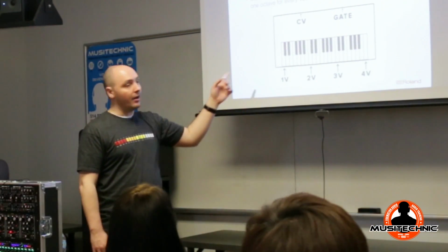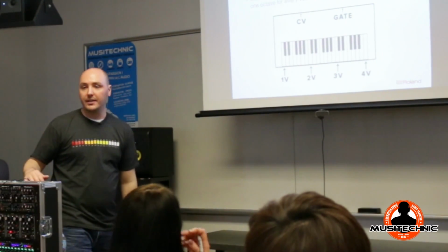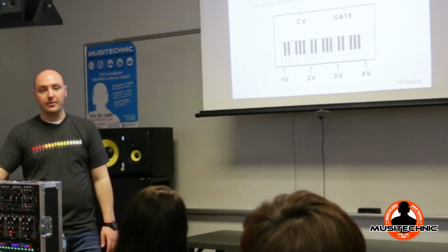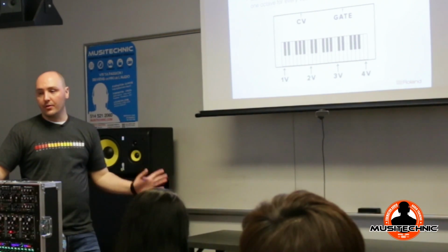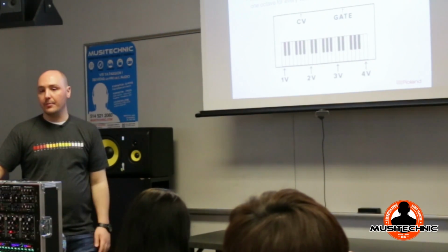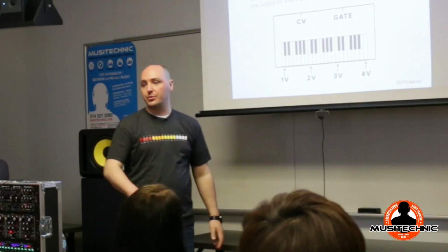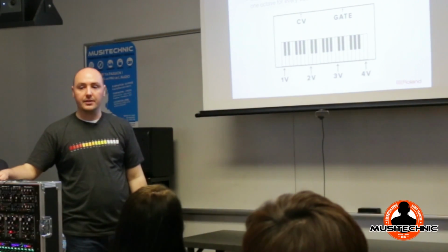And that voltage I will send to an oscillator. I'll talk about an oscillator in a minute, but that makes the sound. So the oscillator knows if it's 1 volt, I play this lower note. If it's 2 volts, I go up 1 octave from that and play that note. So that's what you're using, actual voltage, to control the different modules inside.